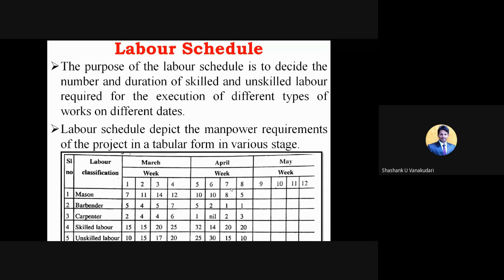So we note down the number of laborers on different schedules, and then provide the required laborers for those activities. We prepare this schedule so that before starting an activity we know how many laborers are required, and can arrange them before starting that activity.